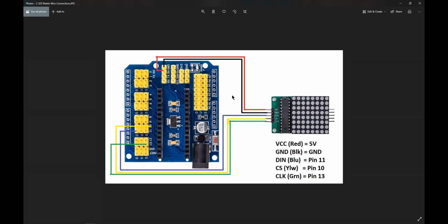One thing you should know is, like I mentioned before, you can definitely drive both the motor and the LED off the Nano. However, it's generally not recommended because after a while it's possible to burn out the Nano, or burn out a transistor or resistor. For the LED matrix, one of them is perfectly fine. If you want to do multiple matrices, you need an external power source. That is, don't power it through the Nano, power it through, for example, a USB power source.